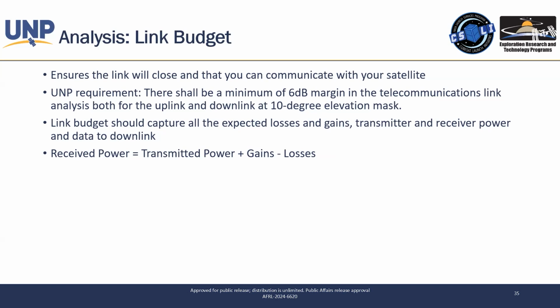There are some flavors of link budgets where instead of the SNR, you'll do what's called Eb/N0. That stands for the bit energy to noise ratio. And that'll take it even further. That'll take into account your modulation and sometimes your source coding.